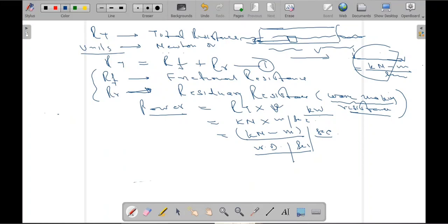Okay. But we have to remember that waves are created because of some energy, because the waves carry energy. So that energy has been imparted to water to create those waves, and that is coming from the ship's engines only, correct? And that is how the engines are causing the thrust on the propeller and the hull is moving. Okay. So that wave making resistance is the residuary resistance. And the sum of these two is the total resistance.